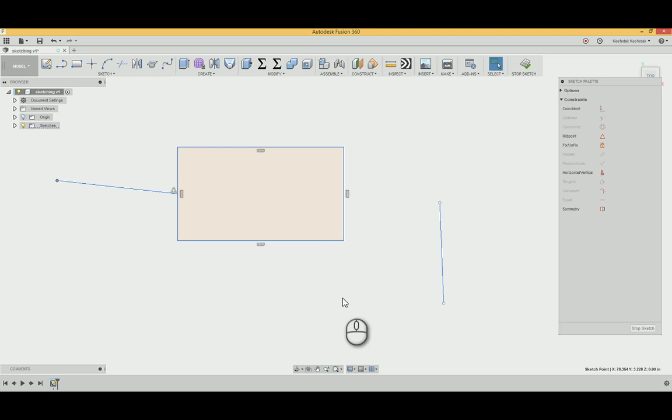Okay. You can also have things be midpoint to each other. So click on midpoint again. You're going to click the line, the other line. Oops, I did. Okay, there we go. That's why I always say clear your cursor with escape, because sometimes you have something selected and you don't realize it, and you apply a constraint inadvertently.